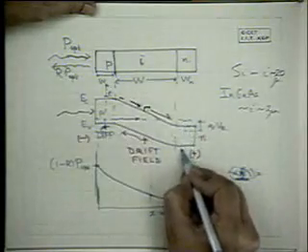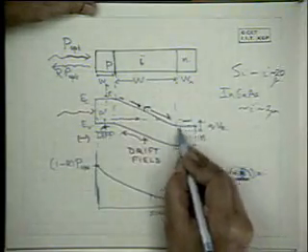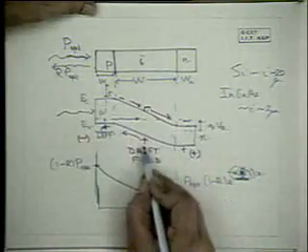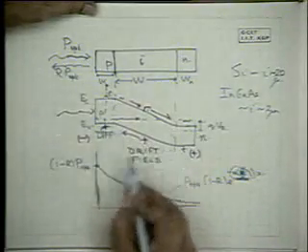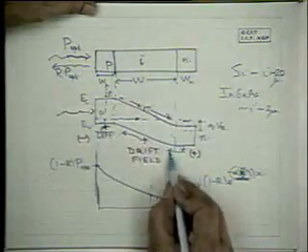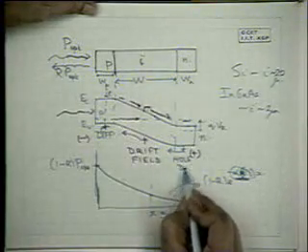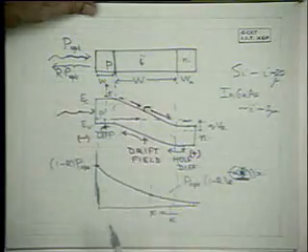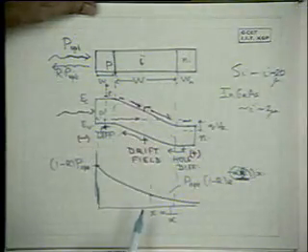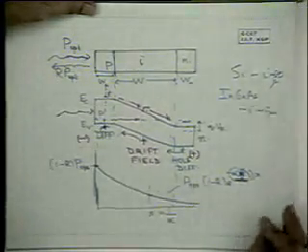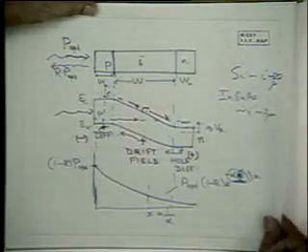So suppose electron and hole pairs are created. There is no field here, so the difference is, here there is an electric field separating the carriers. Here the motion must be by diffusion. So there will be a small current due to hole diffusion. These are the components of current in the PN junction, and one can analyze them.